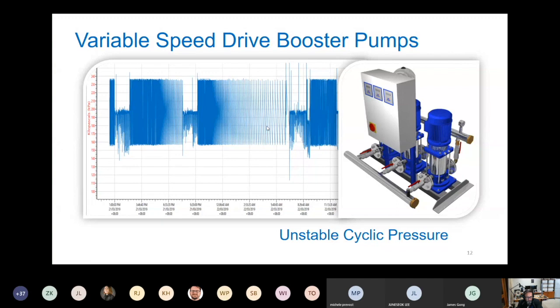The pressure reduction valves at the bottom of the building burst their diaphragms and exposed the apartments at the base to very high water pressures, causing leaks to occur in a building just a week after opening.